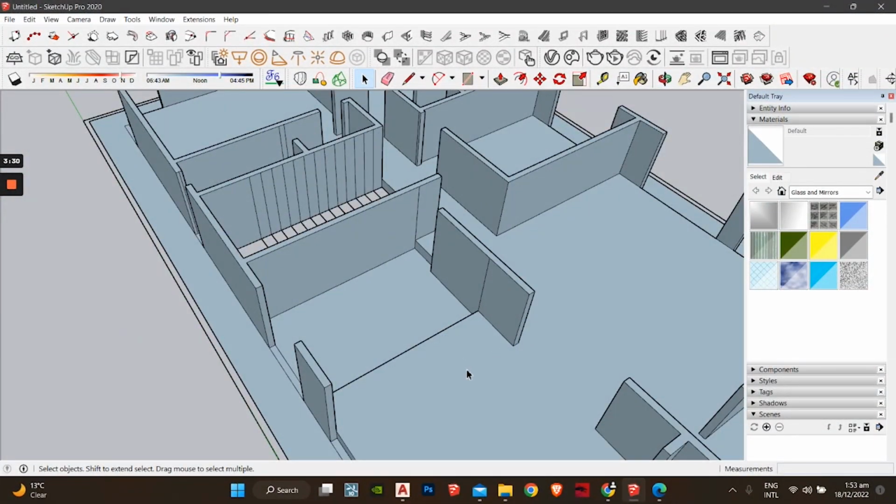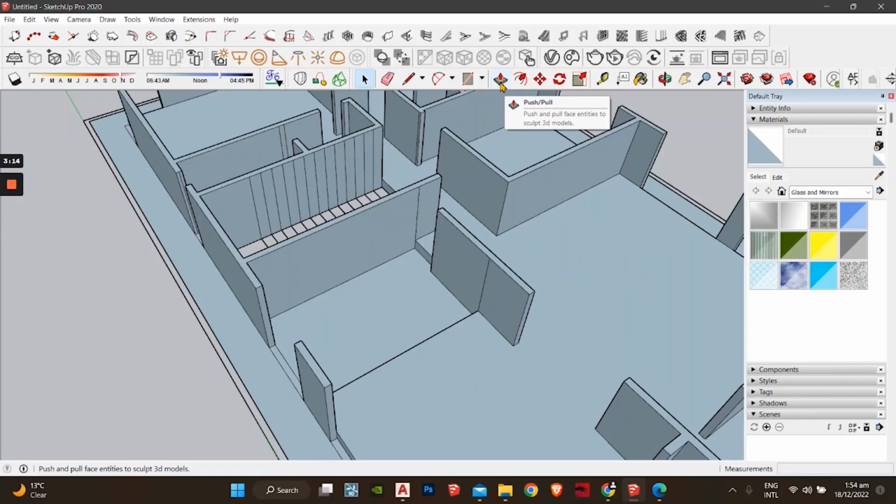When we're dividing a space, it's better to put it at a different level, right? So you can either put it 6 inches up or 6 inches down. It's better to put it 6 inches up because then if you spill something, you literally have a pond. So it's harder to drain the stuff out from there. So it's better to just raise it up 6 inches.